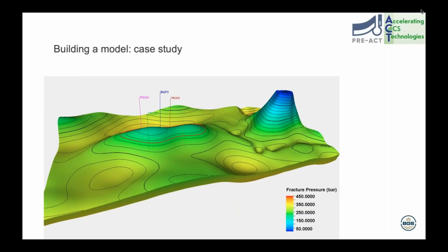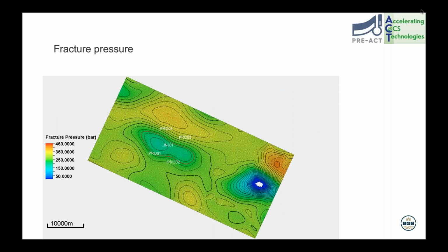So we take a different view of the structure. Injection is via the blue well in the center of the crest. The red wells, the multicolored wells surrounding it, provide a 5-spot pattern that set up our monitoring system for downhole work. The first conformance criterion that I'm going to point you to is defined as the red line that sits halfway down the Endurance structure. This is not going to actually result in CO2 spilling out of the structure, but is chosen as our limit for CO2 movement that we would accept as part of our conformance criteria, and also provides an early warning of CO2 movement towards the spill point.